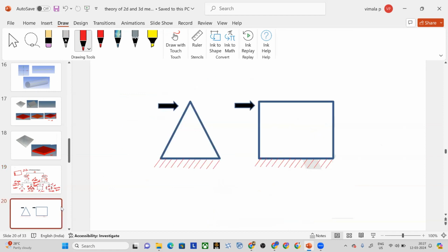Now coming to the point of which element to use. Generally, for any sheet metal or metallic applications of 2D components, you are supposed to use the quad element or quad mesh. That will give you a better mesh, and also a greater accuracy for your analysis answers.